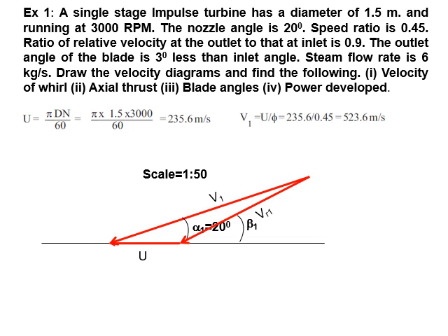Then measure the angle beta 1 by using the protractor. From that intersection point, draw a perpendicular line to the horizontal. That represents the flow velocity at inlet, given by Vf1. So now the inlet velocity triangle is completed.